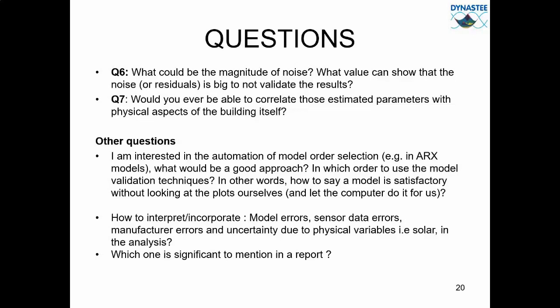So you can say, I mean, bias in sensors will create real problems. If you think that this represents the indoor temperature, and it does not, because there's a bias, maybe you put the sensor in the wrong place, then this will affect your estimates, and that's really difficult to correct for. I mean, that's impossible to correct for. So that's sort of the downside of using data.